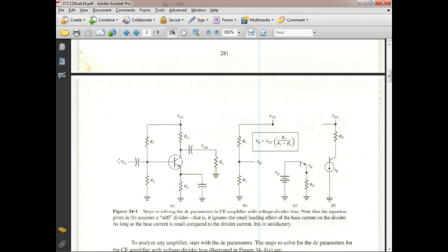What advantage does a half wave have over a full wave? Yeah, it costs a lot less. So if I can get by with a half wave, I'm going to use a half wave. If I can't get by with a half wave, then I'm going to use a full wave. But half waves are cheaper. They're cheaper to build. One diode, one transformer, you got it, right? If I go to a full wave center tap, then I have to have a center tap transformer, and I got to have two diodes. With a full wave bridge, I don't have to have a center tap transformer, but now I got to use what? Four diodes. Well, we get double the voltage out.